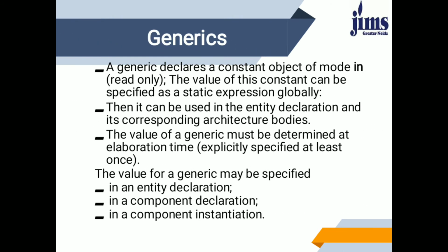With the help of generics, we can declare a constant object of mode in. The value of this constant can be specified as a static expression globally. It is useful as the same design can be used by creating different instances, each having different parameter values. These parameter values, which differ in various instances of the same design, are called generic parameters. So, generics help to generalize a design.